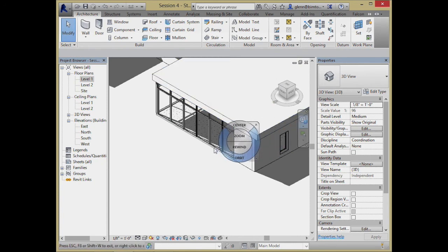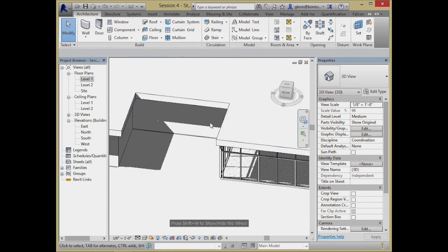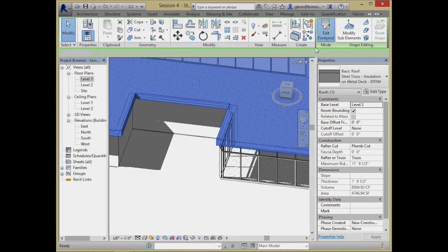At 3 in the afternoon, what's happening is the sunlight's actually coming through that glass pretty well. It's coming this way, through the glass. Things over here on the side are actually in the direct sun at this point, which may or may not be comfortable. So to moderate for that, what we tend to do is put longer overhangs on the building. When you have the south side of a building, or the sunny side, depending upon what part of the earth you're on, you often see people doing this.